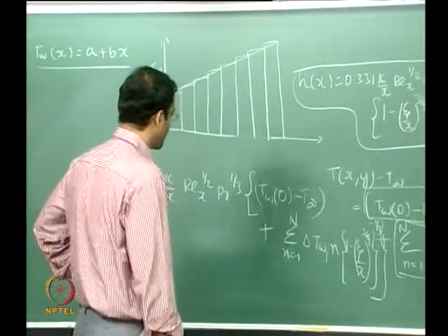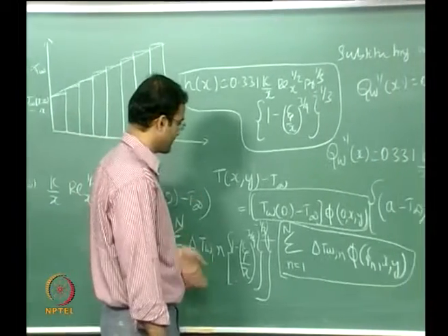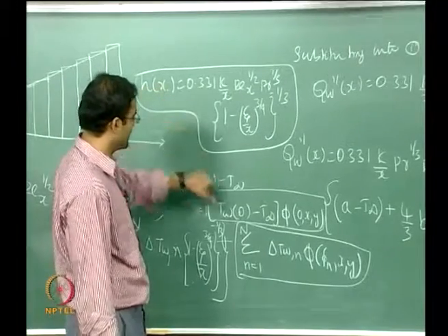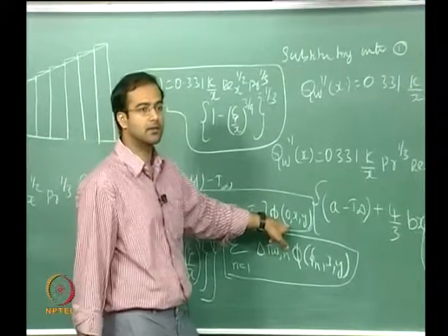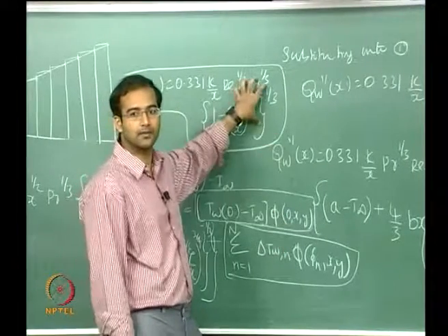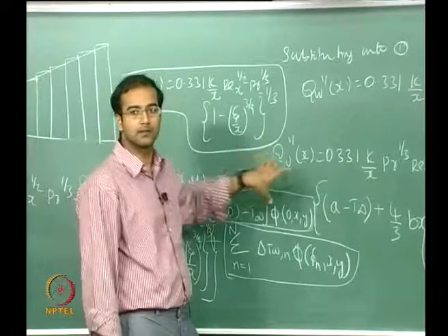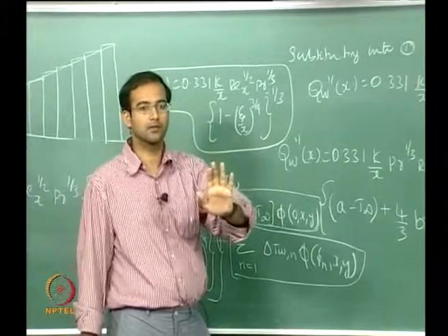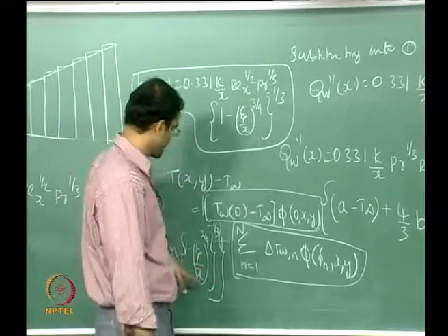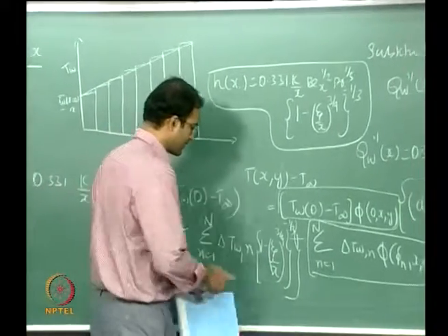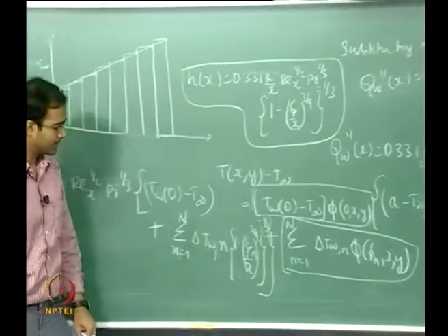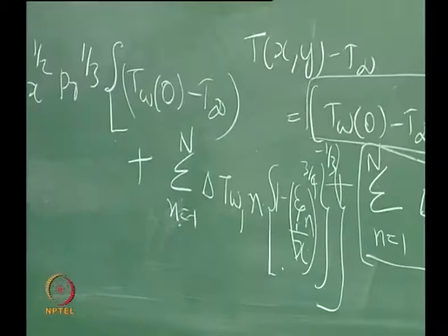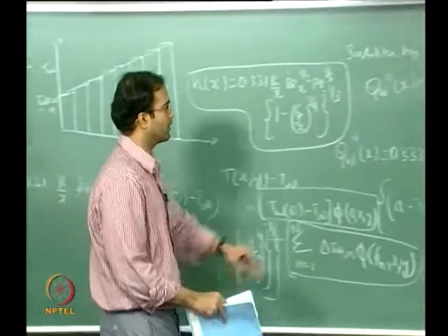Okay, now you have a discrete variation, therefore you just substitute for delta t as it is, and of course the heat transfer coefficient for the first location where zeta equal to 0, there is no unheated starting line, so you do not have this term for that. For the subsequent boundary conditions, zeta equal to zeta 1, zeta equal to zeta 2, there you have an unheated starting line, so you have to substitute the corresponding value of zeta n. Okay, so by doing this also you can calculate your local wall flux variation.